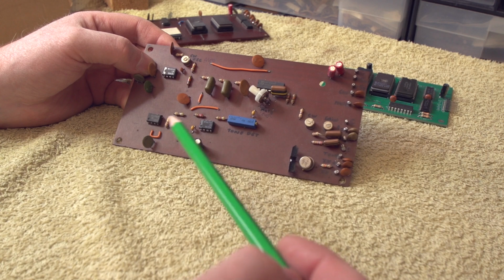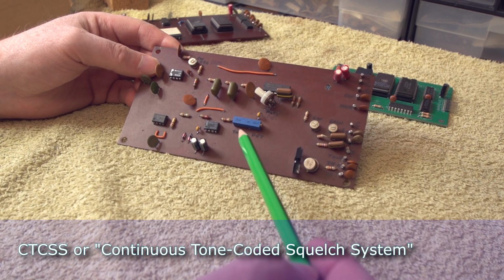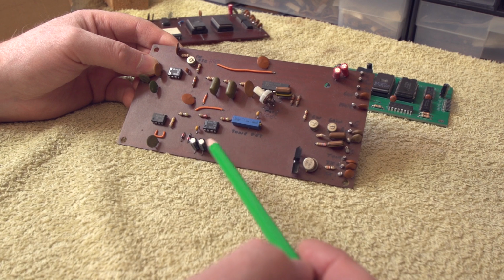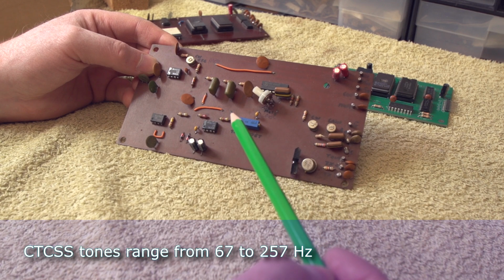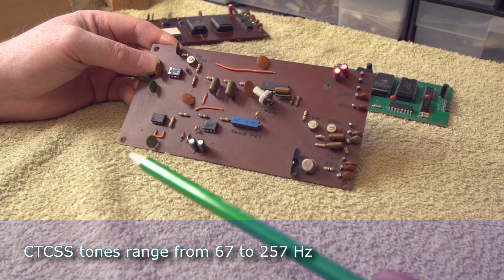That's now been replaced using CTCSS. Now, CTCSS is a bit similar to this. It is a tone coming in, but it's a completely different frequency. It has a range of possible frequencies between roughly 60 hertz and 250 hertz. Sub-audio, in other words, below what you can normally hear easily.